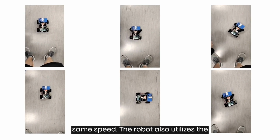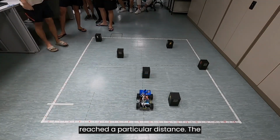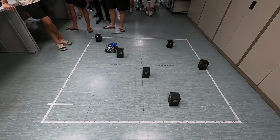The robot also utilizes the encoders to estimate the distance traveled. This allows us to determine when to stop the robot when it has reached a particular distance. The use of gyroscope ensured accuracy for the turns used in Challenge 1.